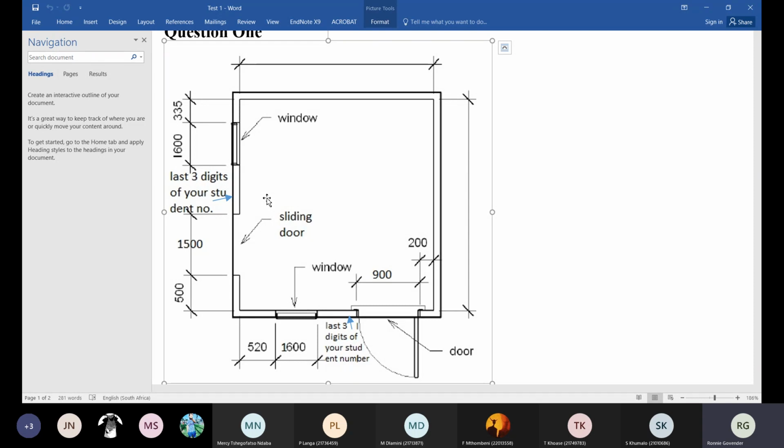Then you would have had to work out the brick force at the gable. Now the gable, the easiest way is very quickly just to draw a triangle. You draw a triangle and you'll work it with similar triangles like the way that I did it in class. You know similar triangles from the mathematics that you did. That is the easiest way.